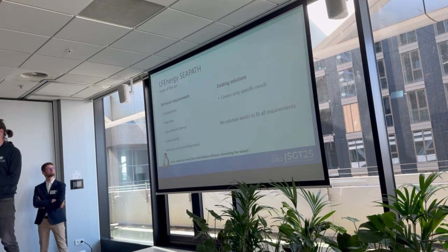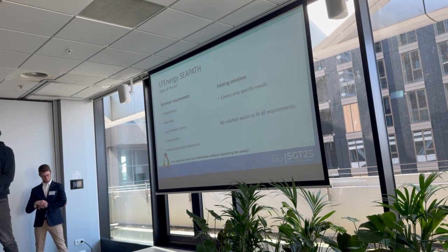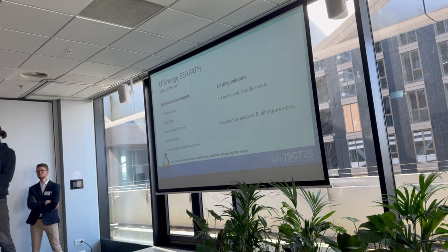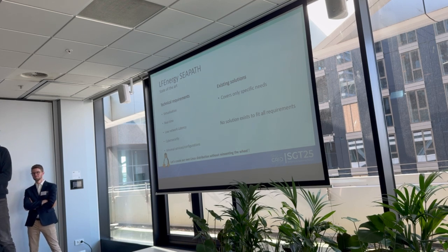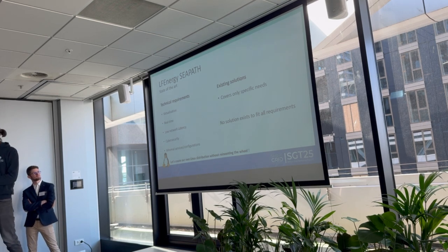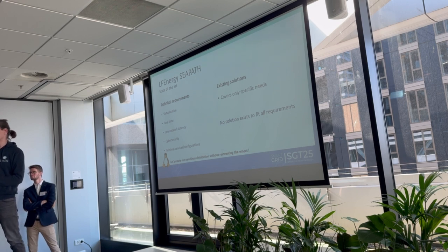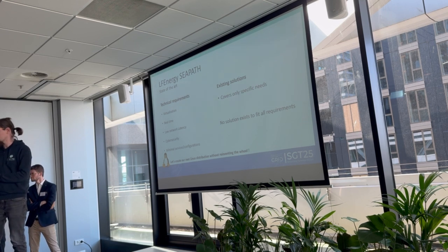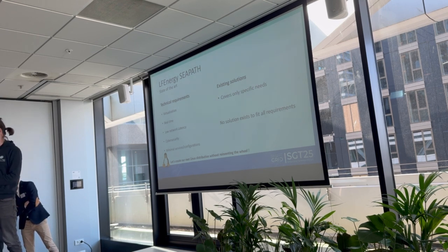Now you have a good understanding of the technical requirements that such a project as Airspace needs. So first, virtualization, of course, to be able to put all these virtualized IEDs. Real-time is also required for protection of virtual IEDs that will come later. Low latency network is also a requirement for real-time. Cybersecurity, because it will be a primary attack target once it is in deployment. And with that comes minimal services and specific configuration for cybersecurity.